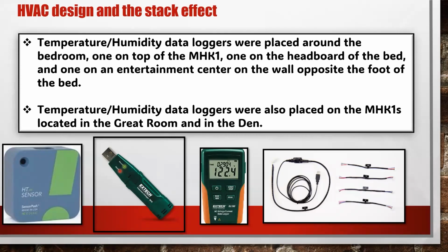So if you get a unit that's 200% sized for the actual load, expect complaints that cannot be solved.